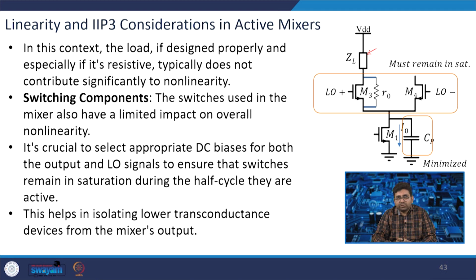Now, the switches used in a mixer also have a limited impact on overall nonlinearity. So, it is crucial to select the appropriate DC biases for both the output and the LO signal to ensure that switches remain in saturation. These switches must remain in saturation during the half cycle they are active.